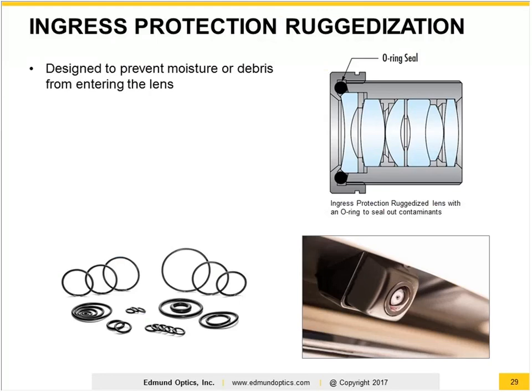So if you look at the image in the upper right here, you'll see that these lenses are here with that simplified focus. It doesn't even have the ring on it in this case that would lock things down. There's no iris, so it has that same sort of fixed set of optics, but you'll notice the O-ring seal that's shown there. Using O-rings or RTV silicone is a great way to seal these lenses up to guarantee things don't get inside. You can seal one end, both ends, depending on the setup, and this will keep you from having things like moisture getting inside, which can lead to humidity and droplets getting inside that will actually deter from the image coming through clearly in the system.